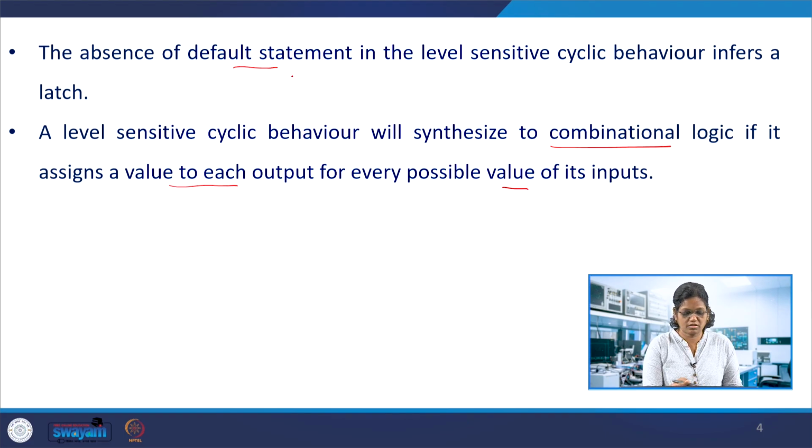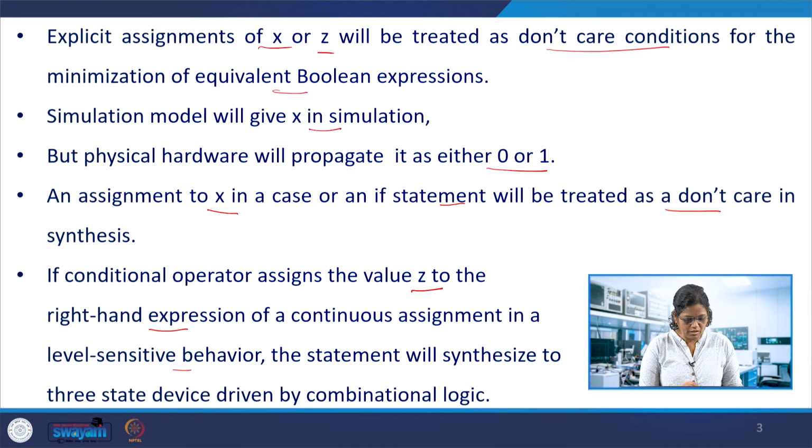Also, the default statement should be there, otherwise it would infer a latch. The conditional operator assigning z will be taken as a high impedance state, whereas x in hardware is considered to be either 0 or 1, but in simulation it is x.